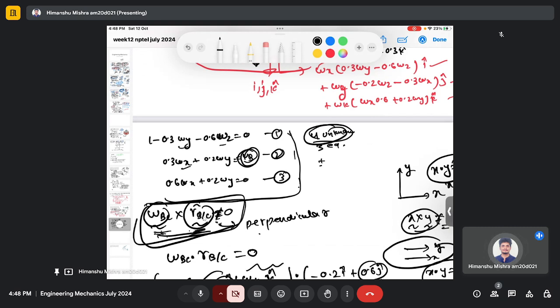So we use this trick to solve. The purpose here is to keep looking for different methods or tricks to find the fourth equation. Like in the kinematics problem or in the equilibrium problem, we used to solve for 3 unknowns by writing down 3 equations: force balance in x, force balance in y, and the moment equation. But if you have 4 unknowns, then you should look beyond these 3 equations.